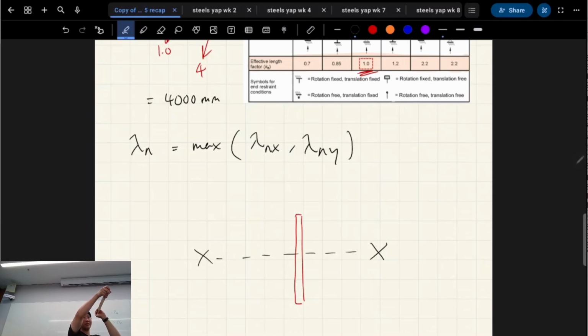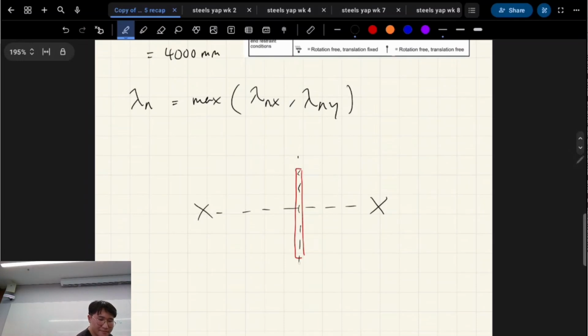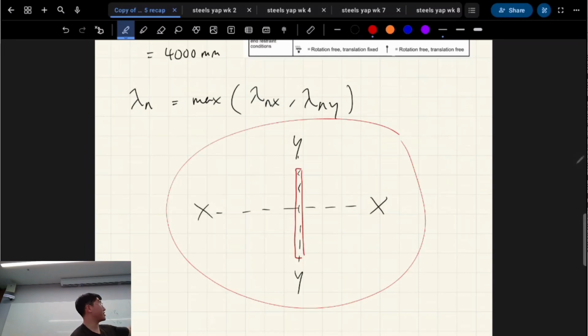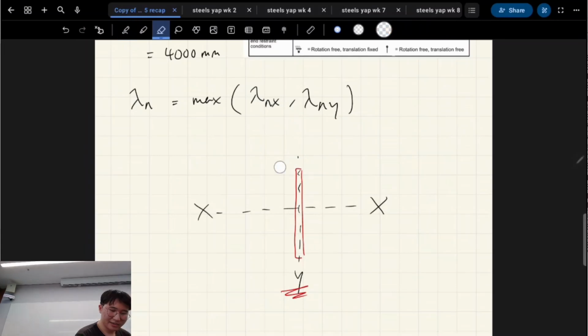It's quite stiff in this major axis direction. If I bend it this way, it's on the side now. If I put axial compression on it, it's going to be less stiff in bending, in buckling, I guess. So what this tells us about this shape, not to do with the shape of our question, is that our slenderness will be governed in the Y direction unless we have heaps of restraints stopping this from buckling. That's an extreme example, but just keep that in mind.